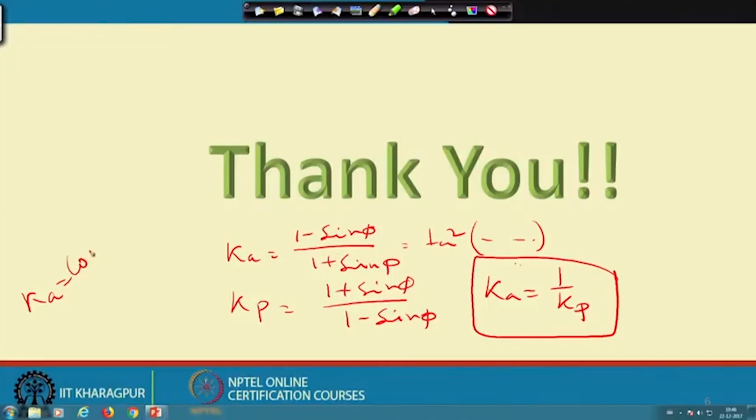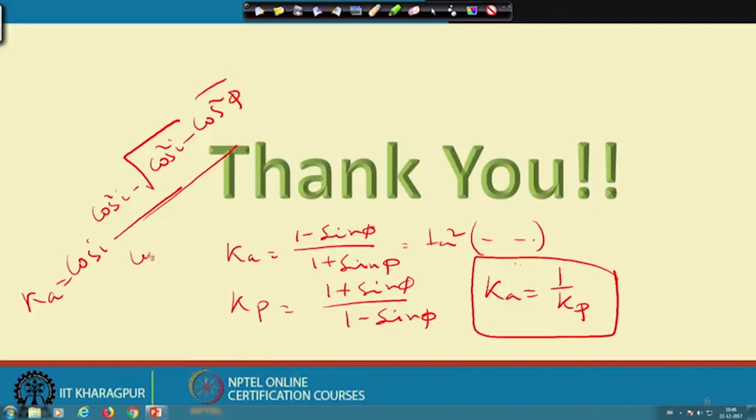When there is a sloping surface, Ka is slightly modified: Ka equals cos i times (cos i minus under root cos square i minus cos square phi) divided by (cos i plus under root cos square i minus cos square phi). The corresponding Kp will have the signs reversed: plus in the numerator and minus in the denominator.